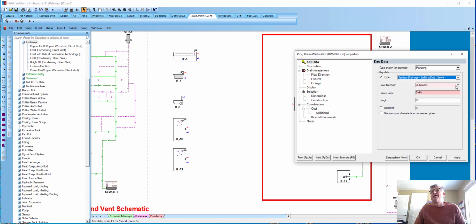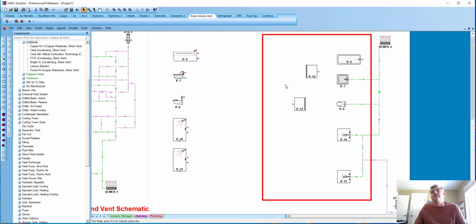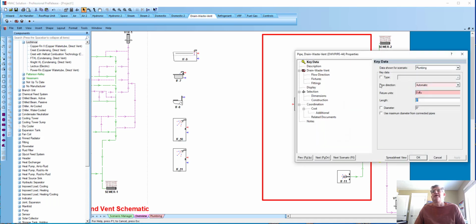And then the flow, we need to give it a flow sometimes. And the flow in that pipe was from the bottom to the top, because that's where I put the sewer line going that way. Now you'll see everything's connected. And if I come in here, do another one, it might be right, it might be wrong. We'll just see what happens. Yeah, and then if I come down here, hook to a vent line, you might see that something might change again. If it does, I got to go in there and just tell it that is a vent line. Okay, it's a branch vent line.